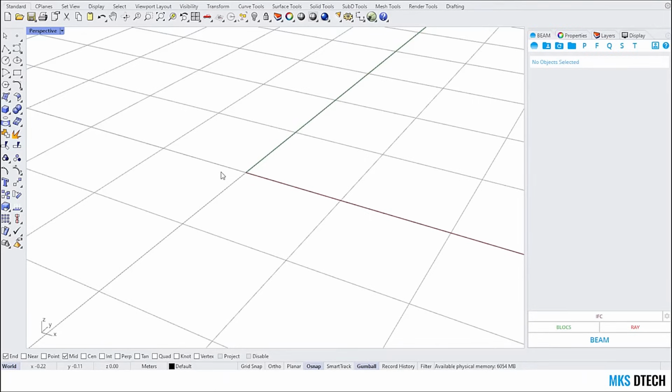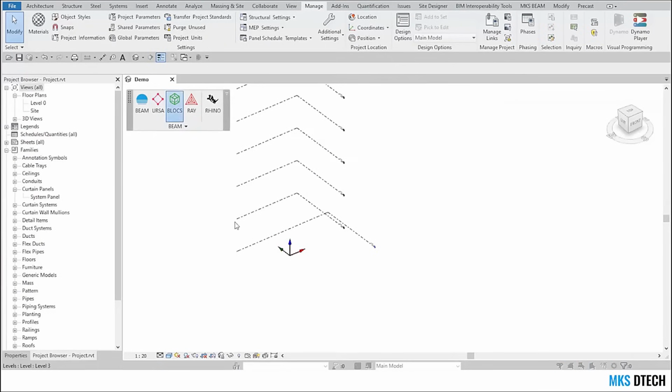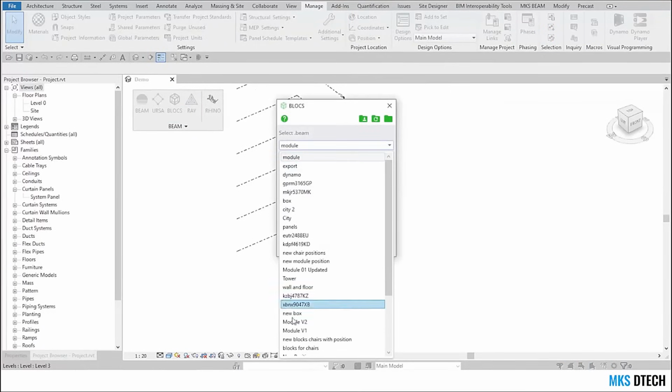Ideally, you can even export the blocks individually into a location on your network, and then you point to that location and go straight to Revit and import it, and it's just like loading a family, because the BIM file will be your family. So you can go to Rhino, export each block individually, save all these files in a folder, and then you go to Revit, point to that directory, and you can use blocks with the list of families from this dropdown. Each BIM file will be actually one block family that can update the components in your file.